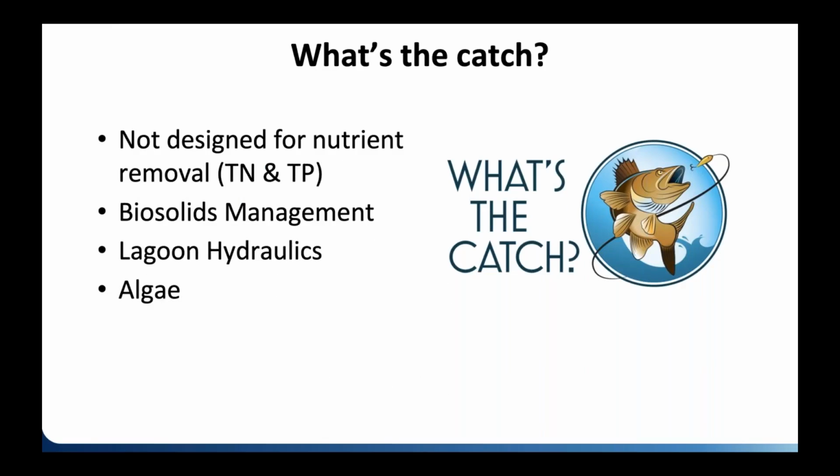So what's the catch? Well, as I mentioned before, lagoons weren't initially designed for nutrient removal. And so if you want to do that, you have to put on bolt-on processes, which does increase operator complication a little bit. Eventually, the whole biosolids management strategy with the lagoon system is the solids sit there, okay? And you do need to remove them at some point. At some point, you got to take the solids out.